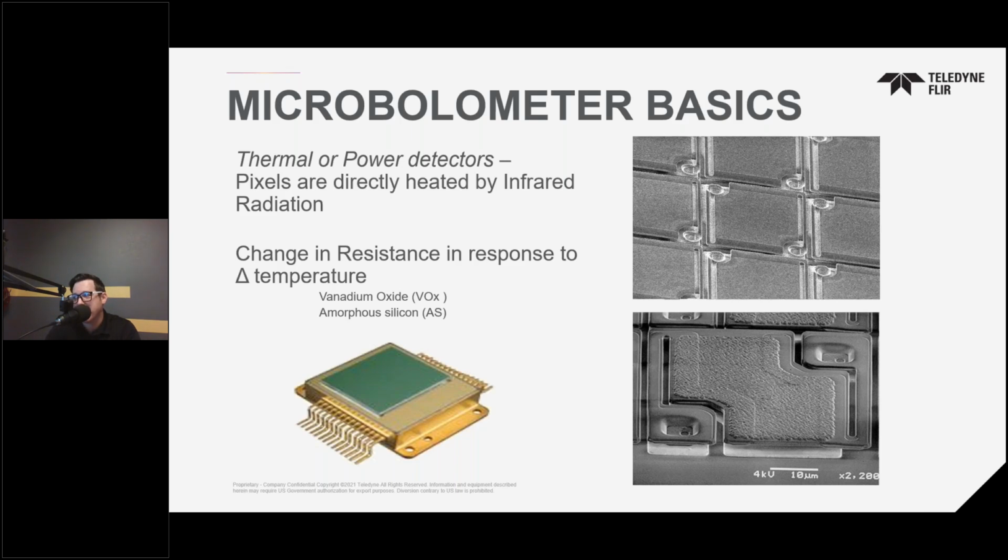Unfortunately, because of the optimization and digital image processing that has to be performed on a lot of the bolometer camera types, there aren't a lot of hooks for a user to perform field modifications, even as simple as applying a filter and then doing a non-uniformity correction. There's just not a lot of hooks there. So typically you'll see a lot of spectral applications leveraging the cryo-cooled cameras. There are some options on the bolometer side, but it's very much rarer.